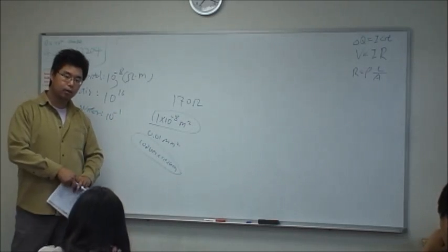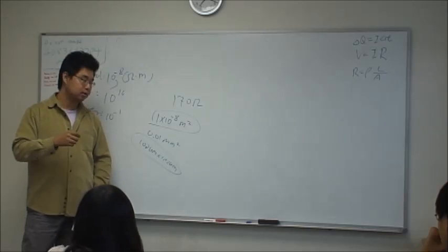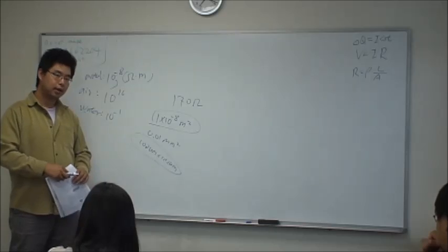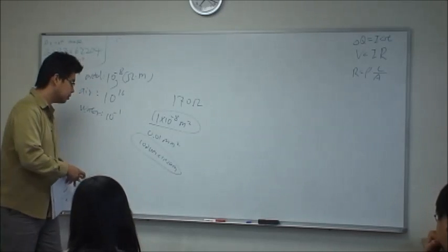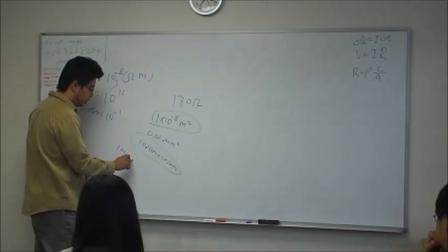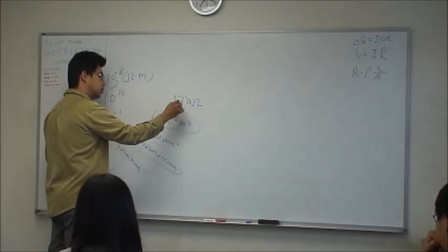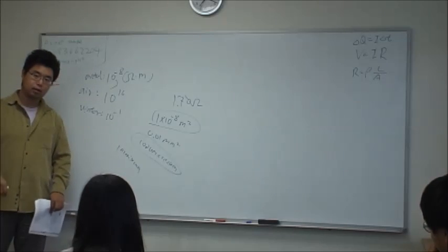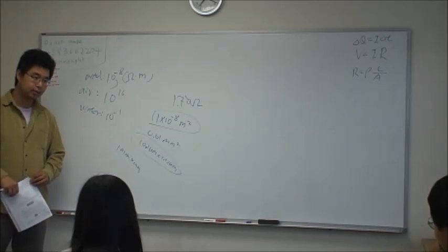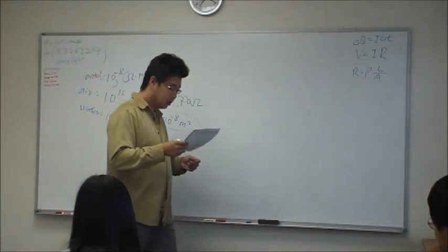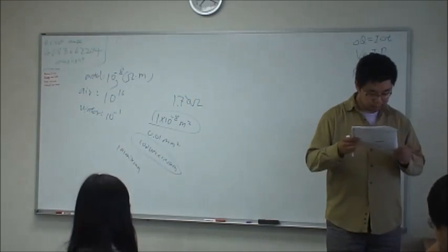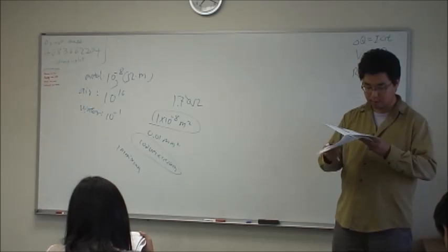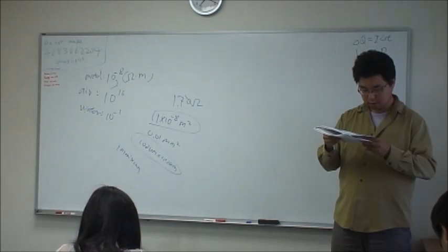So that's why the copper wire we use at home is much thicker, bigger in cross section than this, right? We just need to get 10 times bigger in one dimension. So it means 1 millimeter by 1 millimeter. Then the resistance will be cut by 100 times, 1.7, right? And 1 millimeter is not a big deal. Normal wire is even wider than that, right? So that's okay. Okay, let's keep going. Ohm load, 10 watts battery, so just 10 over 1.7 or 1. So you have the ampere.